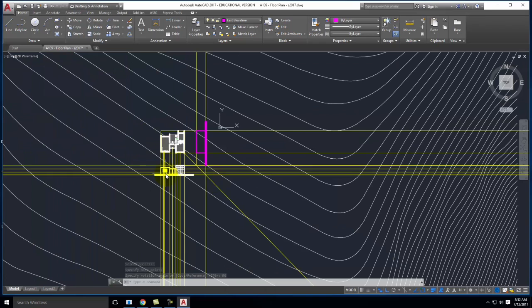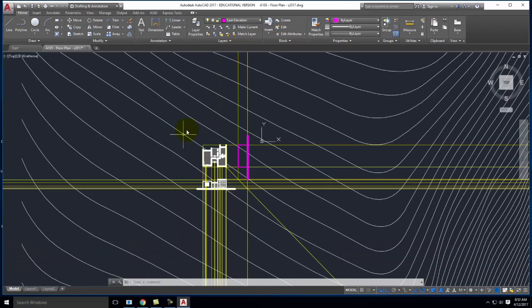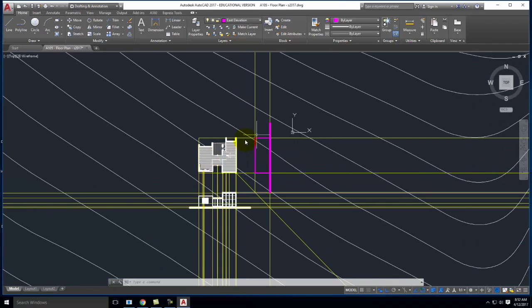So making those rotations, if it helps you mentally, go ahead and do the rotations. The challenge here is that you have to ultimately either keep rotating by negative 90 degrees, draw each elevation, and then you end up in the correct orientation again, or you have to rotate backwards to get into the correct orientation. Otherwise, you can, of course, just draw it to the side or upside down or backwards. We're going to leave these in their positions folded out from all the elevations, and I'm going to show you how to reorient them on a paper space model later on. So the goal today is to be able to create each of the elevation views, north, south, east, and west, of your plan.